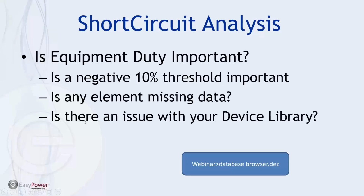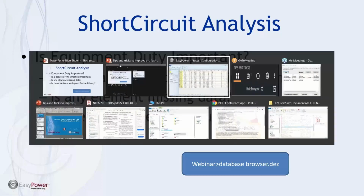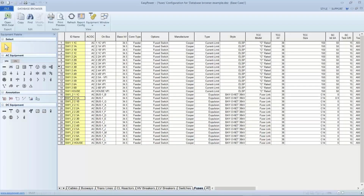Now, once we've got our database cleaned up, the next step is going to be doing short circuit analysis. So as we've seen, as I go to short circuit focus, anything with a minimum of data will be highlighted, but are we going to get the correct results as far as equipment duty? Let's go back and look at this.